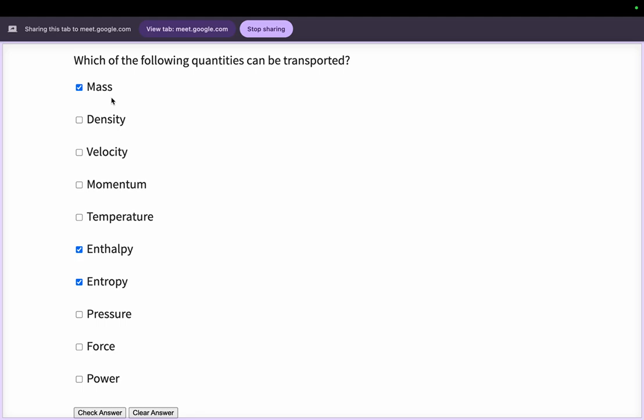So for example, for mass, we know that mass can neither be created nor destroyed under normal conditions. So we will say that if at some particular point A mass has decreased, it means it has moved out of A to somewhere else B. Because mass can be transported, we can write equations like that. So it is important to know which can be transported and which cannot, without which the equations do not have meaning as such. So I would encourage you to think a little more, you are on the right track, and come up with a better criterion. So is velocity a transported quantity?